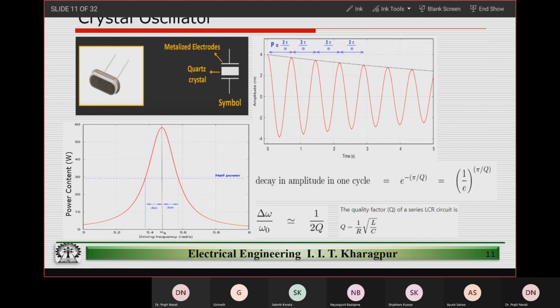So this is important, guys. This is very important. Not many people will tell you this. When you are giving an input step to an amplifier, and the amplifier output settles, by counting the number of peaks that are there, you can actually get a measure of the phase margin of the system. So you need not always run an AC analysis to get a measure of it.